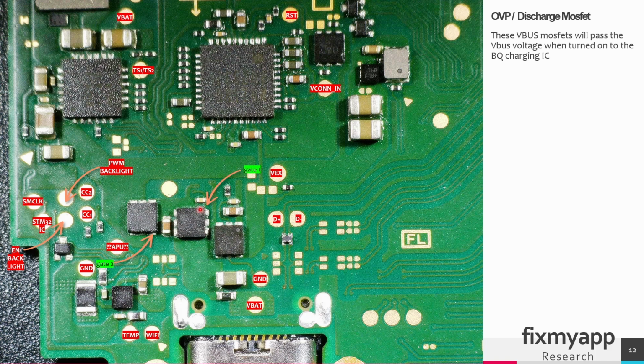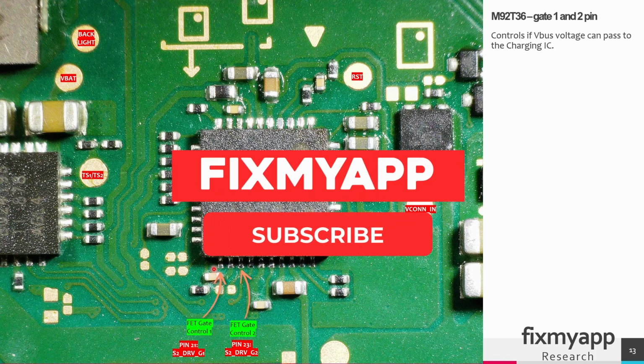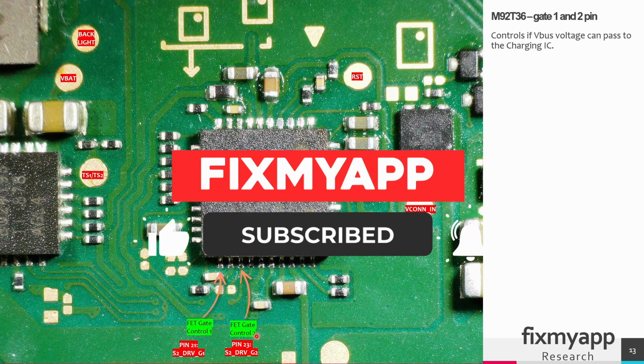Controlling this MOSFET 1 and MOSFET 2 is done by gate 1 on this pin and gate 2 on this pin. This gate is directly connected to the M92 IC, so the power delivery IC. If you look at the power delivery IC on pin 21 and 23, the gate of MOSFET 1 is controlled here and the gate of MOSFET 2 is controlled here.